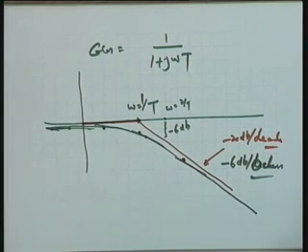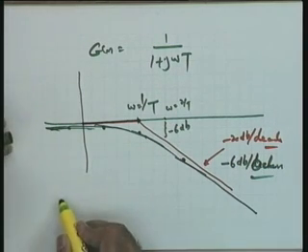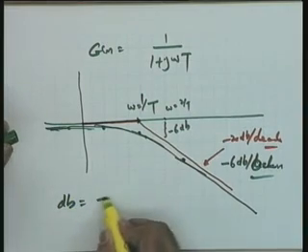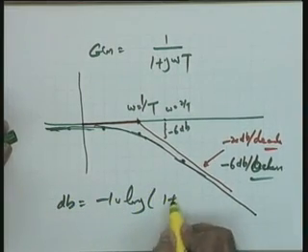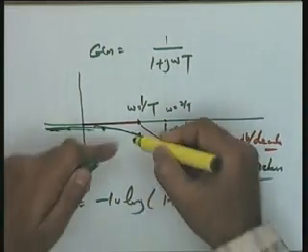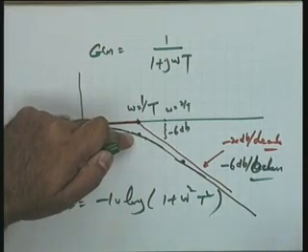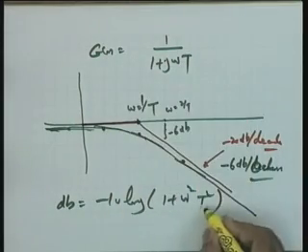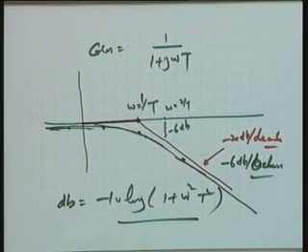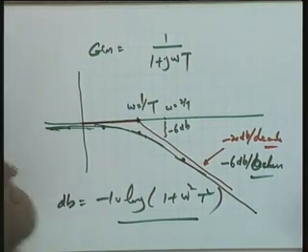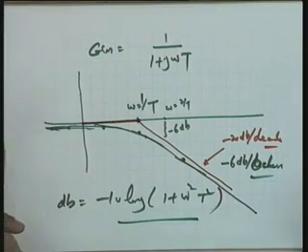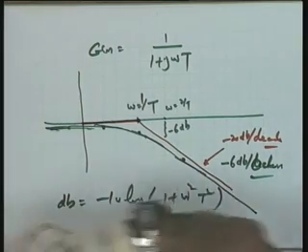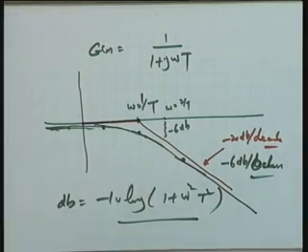So how does minus 3 dB come, sir? The actual value is dB equal to minus 10 log of 1 plus omega square t square. This is the actual value corresponding to the green curve. An approximate value we have taken is 0, dB is equal to 0. So omega equal to 1 over t gives you minus 3 dB, that's all. And identically for omega equal to 1 by 2t or omega equal to 2 by t, it is a simple calculation, subtracting from the asymptotic value. Okay, so this way we get the green curve.